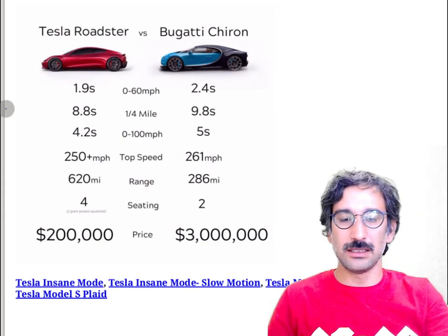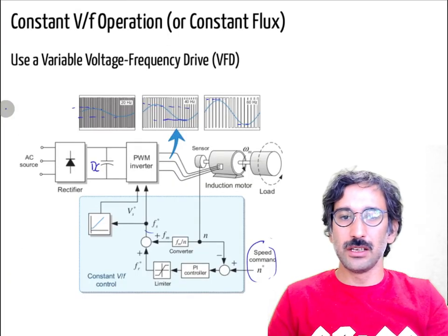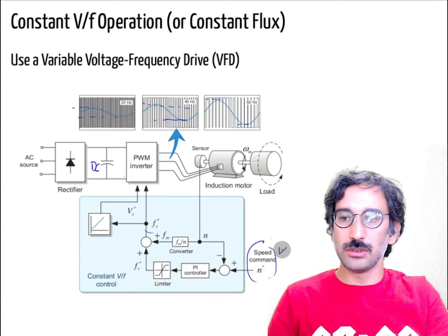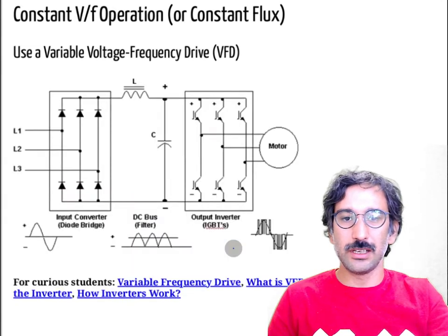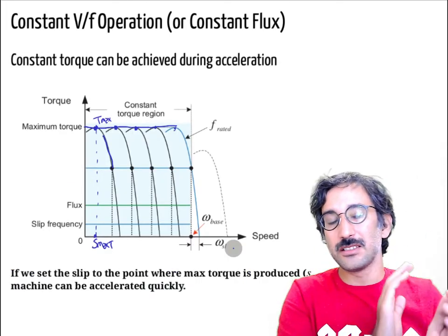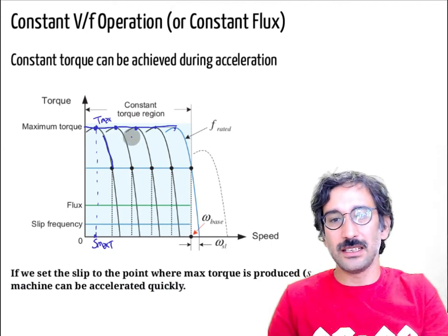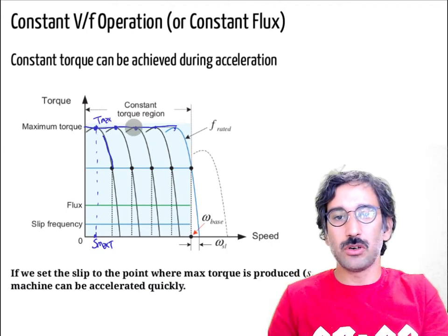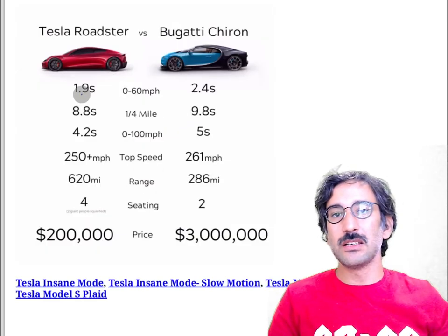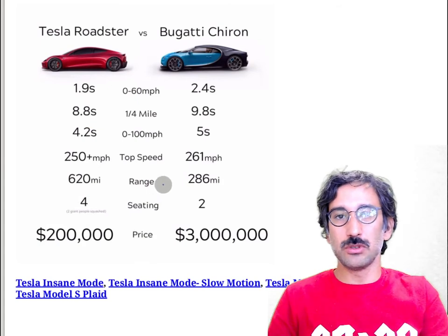But for Tesla Roadster, you have that kind of PWM controller. Okay, I want to go to that speed with the maximum torque available, so I can start turning my transistors precisely just to keep the motor at maximum torque during acceleration. So you can go from 0 to 100 kilometers per hour. It's less than 2 seconds.